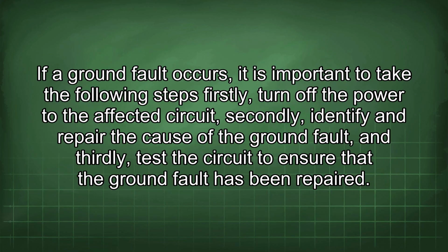If a ground fault occurs, it is important to take the following steps. Firstly, turn off the power to the affected circuit. Secondly, identify and repair the cause of the ground fault. And thirdly, test the circuit to ensure that the ground fault has been repaired.